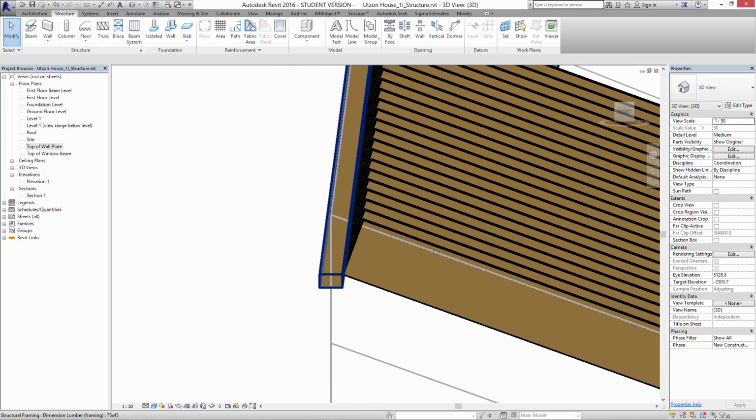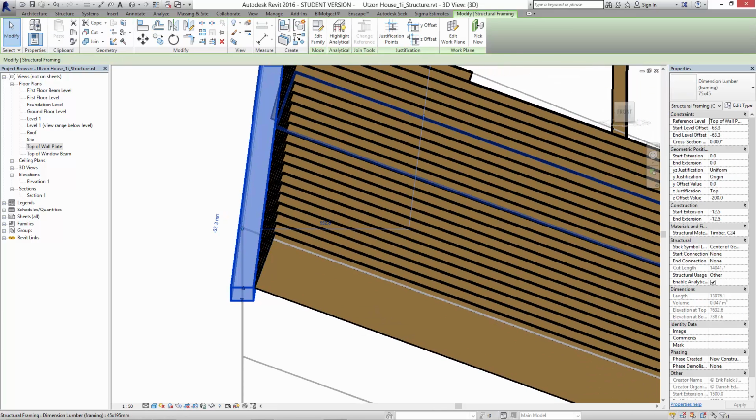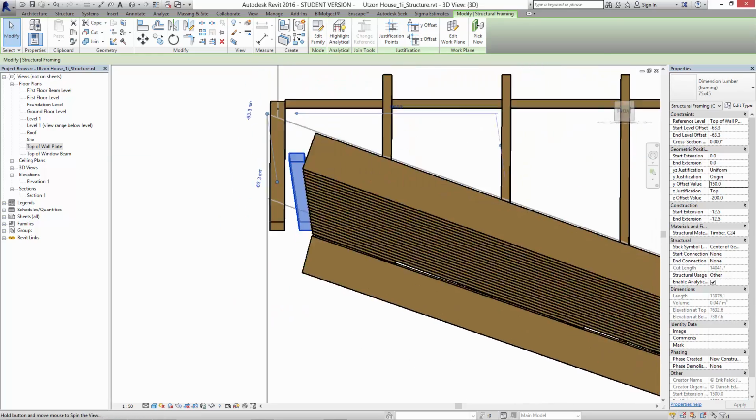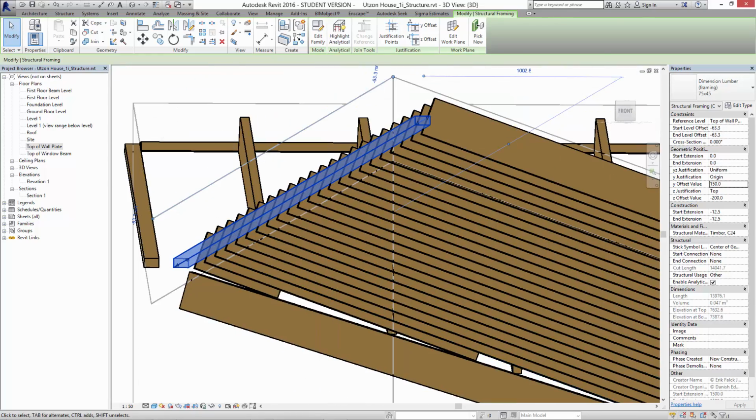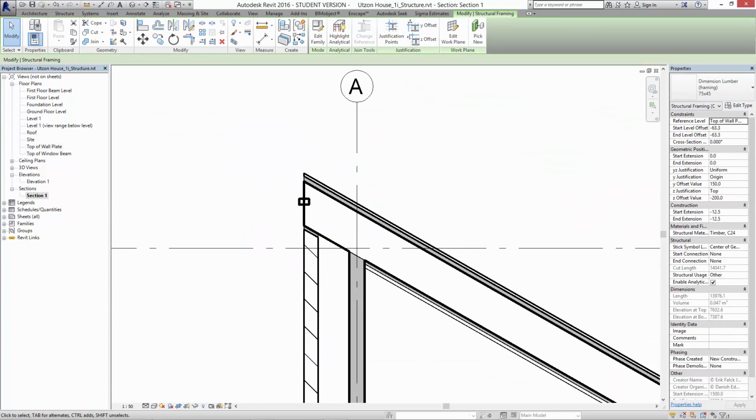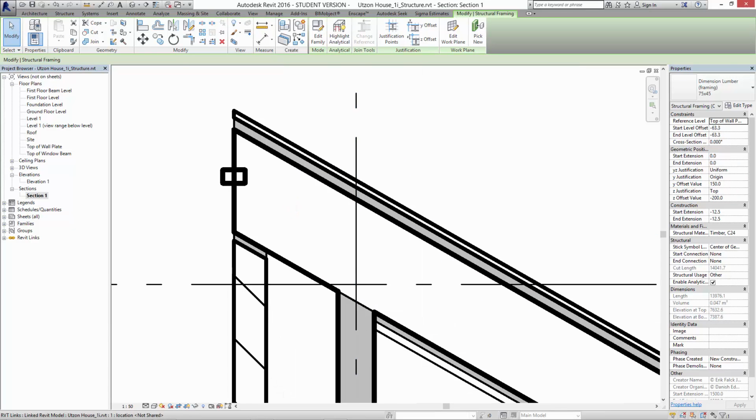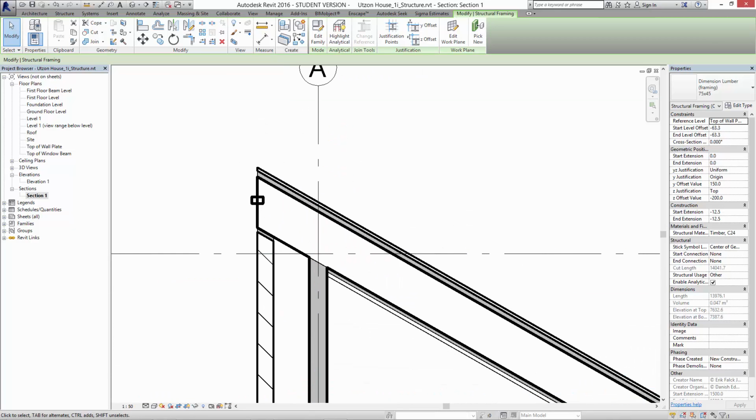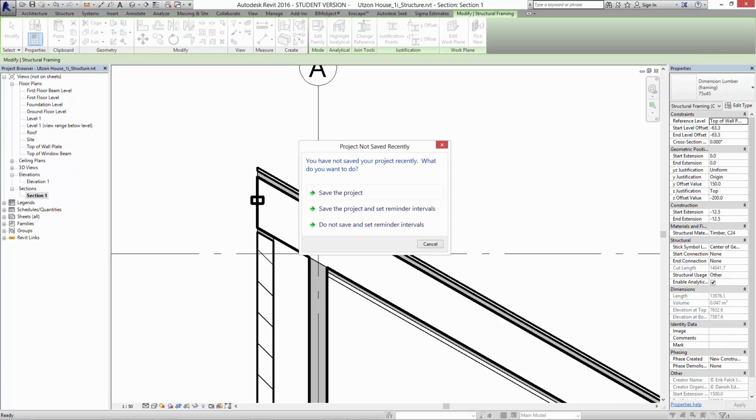So we can do a couple of things. Like we can take the beams we've put in there, we can modify their position. So we could offset them by either Z value, Y value. So if I offset this by, let's say, 150, just to see which way it goes, it's coming back into the building again. So you can place this very accurately using this section. The moment it's up here, it doesn't really comply correctly. That's why I'm saying you should probably place things according to level rather than just picking by lines if you can possibly get away with it on a simple project anyway.